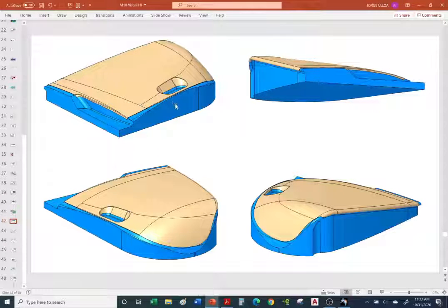Okay, so the problem is when you stick this in an autoclave or small oven, or you heat it up, the mold will increase in size due to the heat. So when you heat this up overnight, and the next day you take it out, the piece is going to come out larger than you want, because the mold increased in size due to the high temperature. And then when it dried, the piece came out larger than expected. So you have to change the scale. And typically we would reduce it by 0.02%.